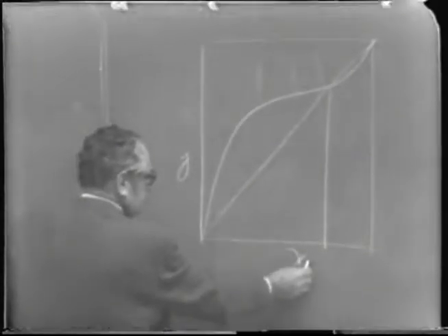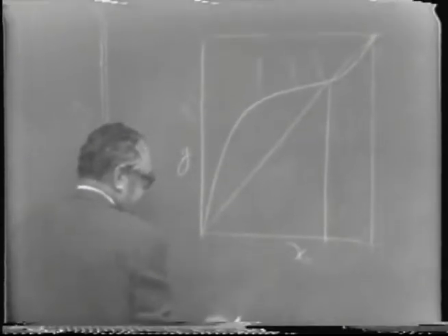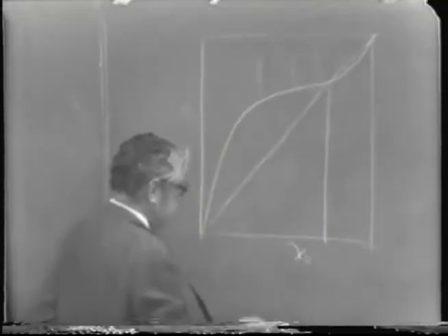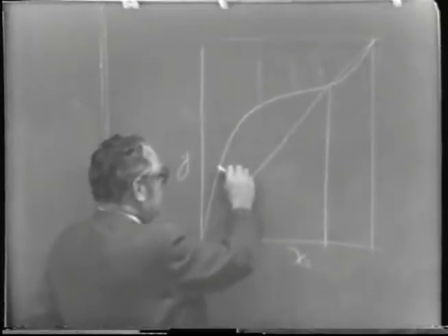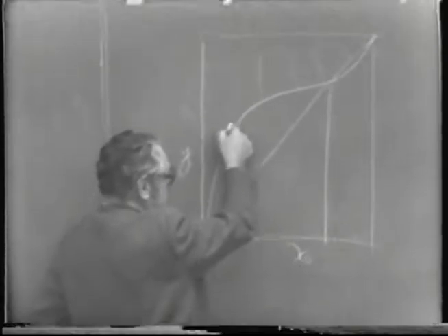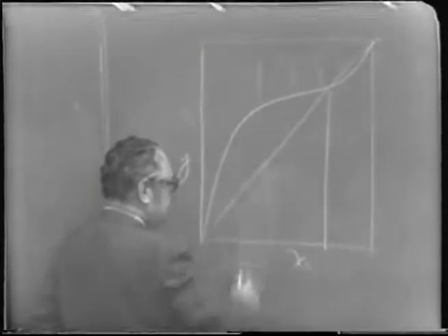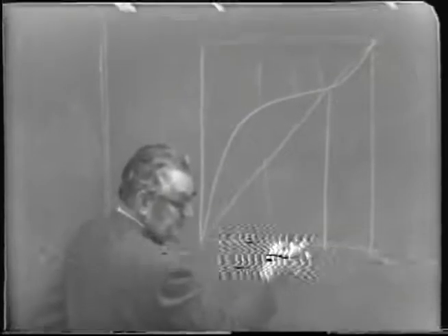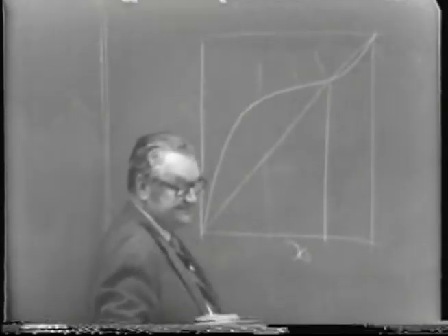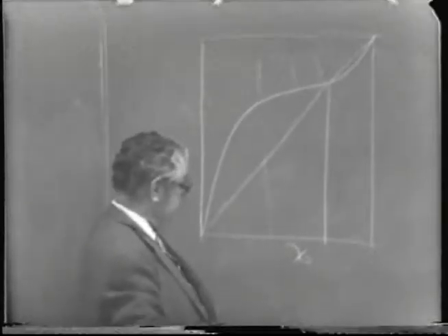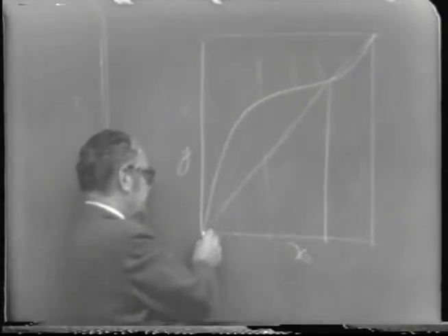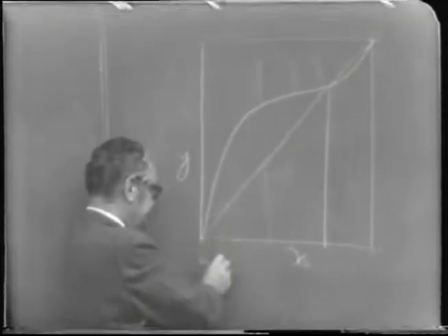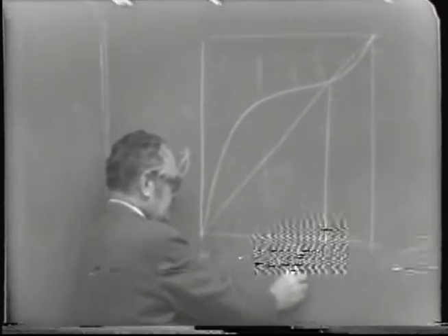And so in this region here, component A, as we've illustrated here, is more volatile than component B because the equilibrium curve is above the line. So you can separate any particular feed mixture in between into the more volatile material, which is the azeotrope, as the top product, and the less volatile material, this would be 100% A or B here. X of B would be this way.